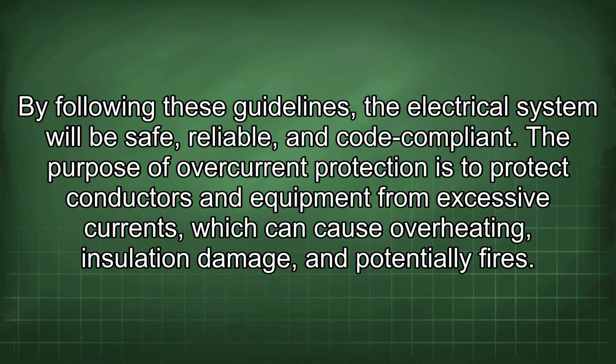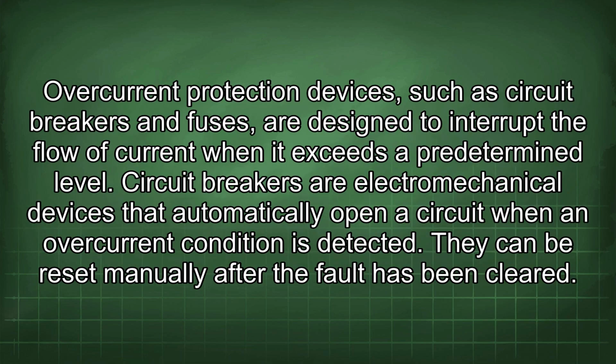The purpose of overcurrent protection is to protect conductors and equipment from excessive currents, which can cause overheating, insulation damage, and potentially fires. Overcurrent protection devices, such as circuit breakers and fuses, are designed to interrupt the flow of current when it exceeds a predetermined level.